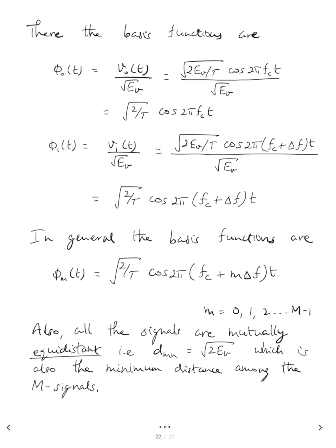Those will be topics for the next session, but for now let's quickly summarize: we have seen how to create baseband multidimensional orthogonal signals and also bandpass multidimensional orthogonal signals. One simple way of creating bandpass multidimensional orthogonal signals is to have frequencies separated by a certain value, that is orthogonality in the frequency domain. By choosing the appropriate frequency separation, we can ensure that the frequencies are orthogonal to each other.